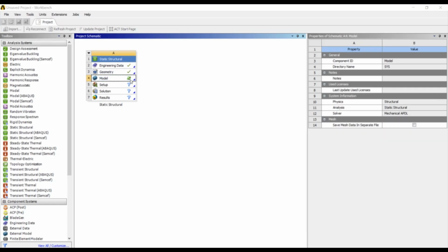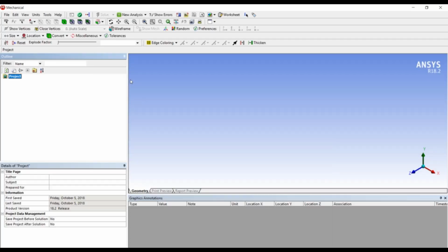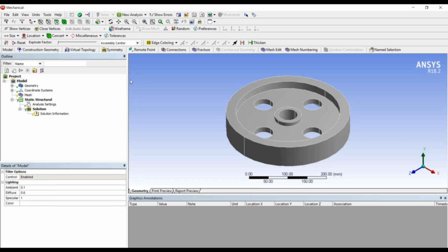module, or ANSYS mechanical module. Once I have opened this, we are going to perform the analysis using the total body, and once we see the results, then we are going to reduce the size of this particular geometry using symmetric options. Then we are going to again perform the analysis and try to compare the results coming from both of the analyses.